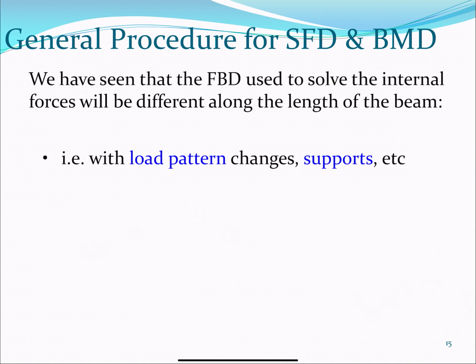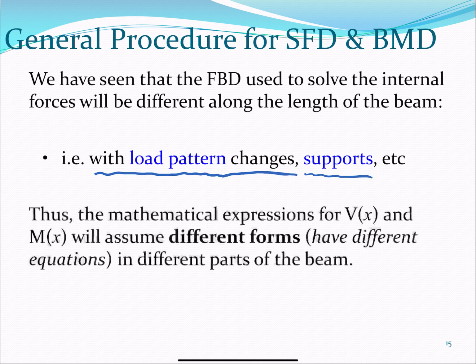So, things to notice. We have been using free body diagrams to solve for the internal forces, and we have to be careful to identify the segments. It's important. These segments will change when the load pattern changes, when you have supports, etc. So you will have different sets of equations in different parts of the beam.